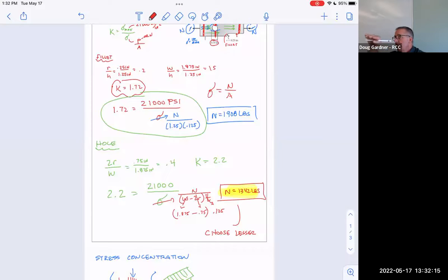It's like the concrete's cruising along and then suddenly it necks down, and instead of being 3 inches thick, all of a sudden it's 2. What's that going to do? It's going to take whatever force is in it and concentrate it right there so that it breaks right there. Well, what happens when it breaks right there? Well, it's down in a hole and you can't see it.